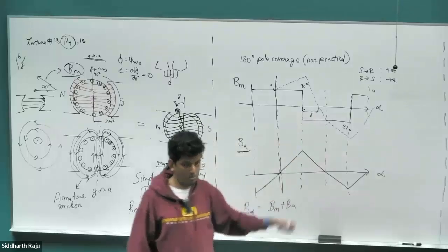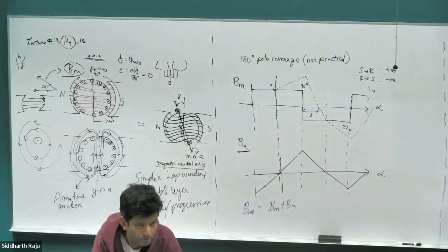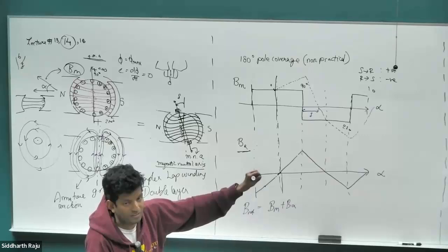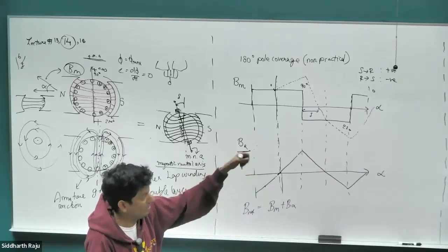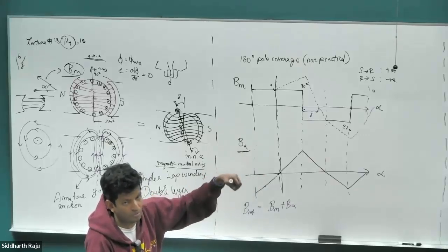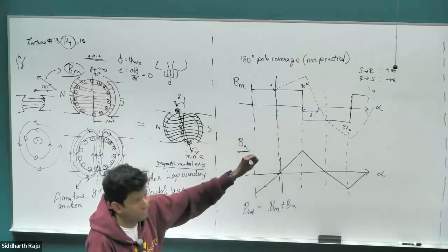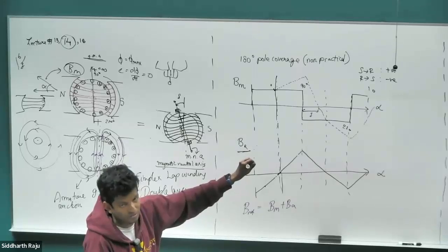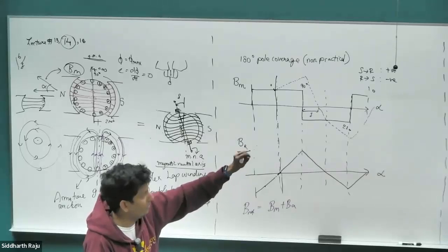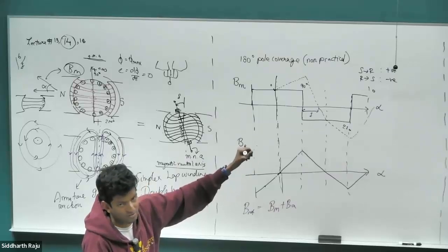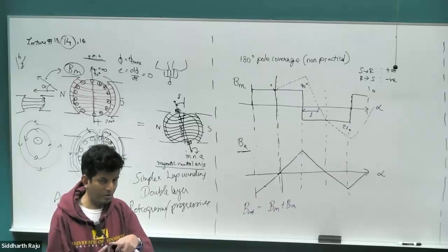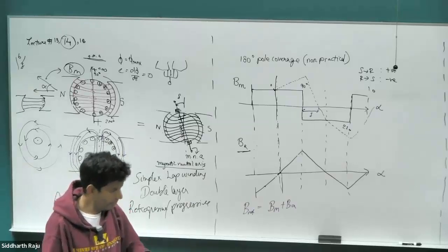Maybe I'm missing something, but are we ignoring the H field inside the magnet itself? H field inside the magnet. Yeah, we're going to assume this is a ferrite magnet, or if it's a salient pole, where we have an iron core on which a coil is wound, it's an electromagnet. So we're going to assume that has infinite permeability as well. If we have a neodymium magnet, the situation becomes a little bit trickier. There would be no saliency, which we will introduce later, in this magnet when we have a neodymium magnet in this place. For the motor that we have on the table here, we do have an Alnico 5 magnet inside. Okay. Any other questions?